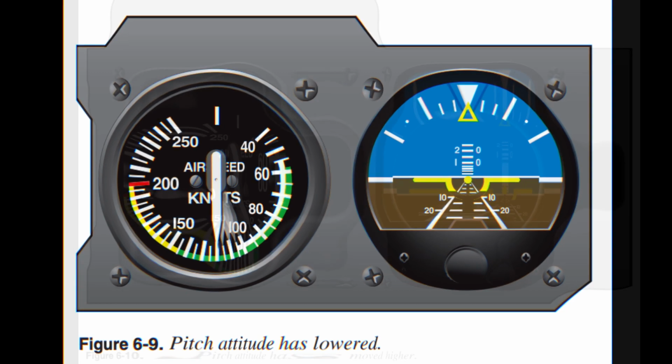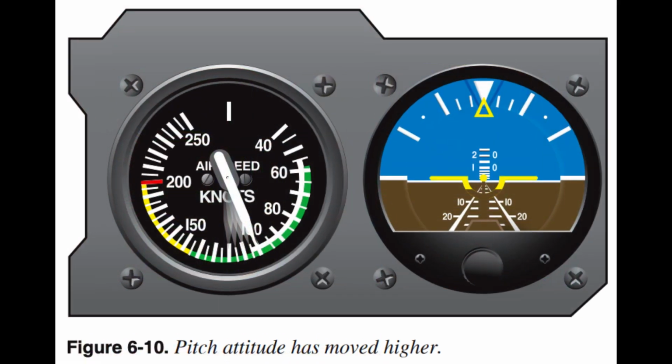Figure 6.10. A rapid change in airspeed indicates a large change in pitch, a slow change in airspeed indicates a small change in pitch. Although the airspeed indicator is used as a pitch instrument, it may be used in level flight for power control. Changes in pitch are reflected immediately by a change in airspeed. There is very little lag in the airspeed indicator. End of page 6-6.